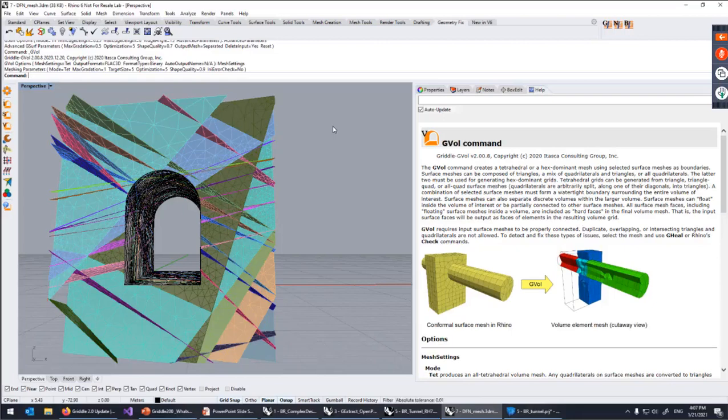And that's why it's important to visualize these meshes and maybe visualize specific elements, let's say tiniest elements or bad shape elements within Rhino, so you can play with different parameters and quickly decide which parameters to pick. So this is something we plan to do in a future version of Griddle or maybe in some updates. For now, basically, you have to play with parameters, load your model into modeling software and analyze it there to see if the elements are what you need.